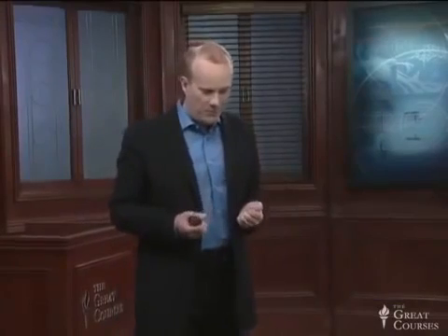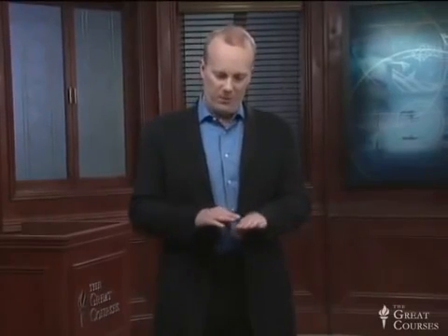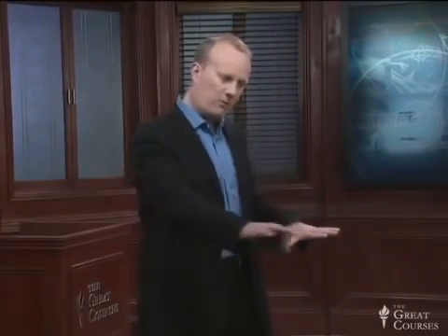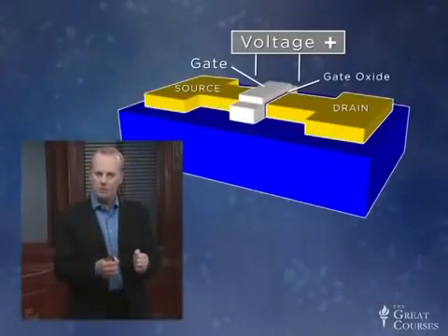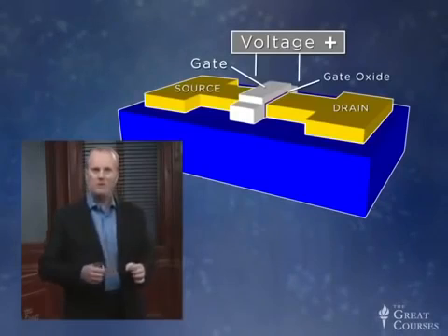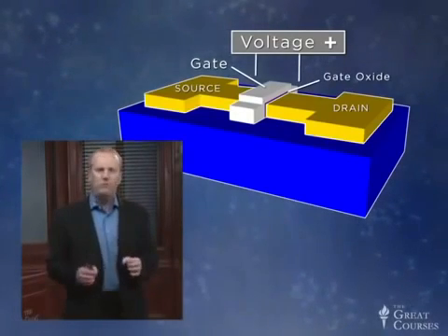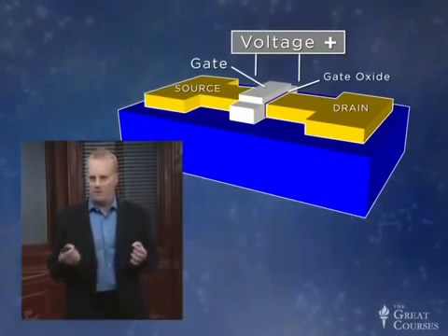Now, there is another challenge that comes here, which is we thought we were doing planar lithography, right? We thought that we were just building kind of a two-dimensional circuit. We were kind of working in a flat landscape, and then we were just putting materials here and there and there. But to wrap a gate around the channel involves etching into the silicon. It involves digging down into a little trench. And when we do that, there's the possibility of making damage.